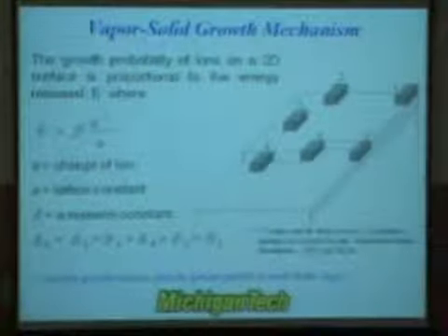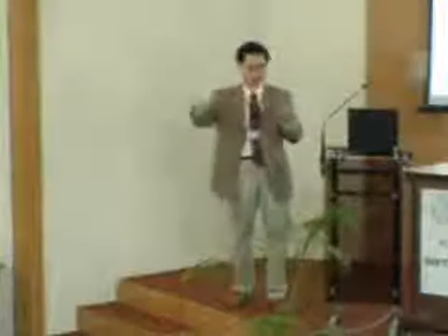And at the same time, if you look at the nucleation theory, you find that if you have a perfect atomic surface like this, you have only 1, 2, 3 possibilities for the atom to land on the surface. And you will see that number 1 and 2 are the preferential sites for the growth. So, which means if you can cool down your growth conditions so that there is no growth at the center of the rod, they will confine the growth at the edges, just like what I show here, right?